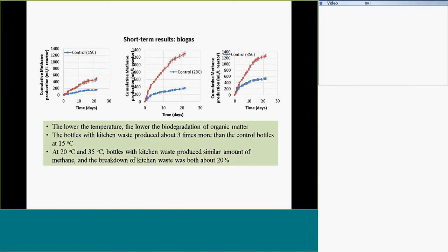So one is 30%, but it produces way more methane than the other 70% of sludge. So that indicates that food waste is more degradable when you flush food waste to the septic tank. It's not going to increase the total suspended solids in proportional ways in the substrate, because a lot of them will degrade.